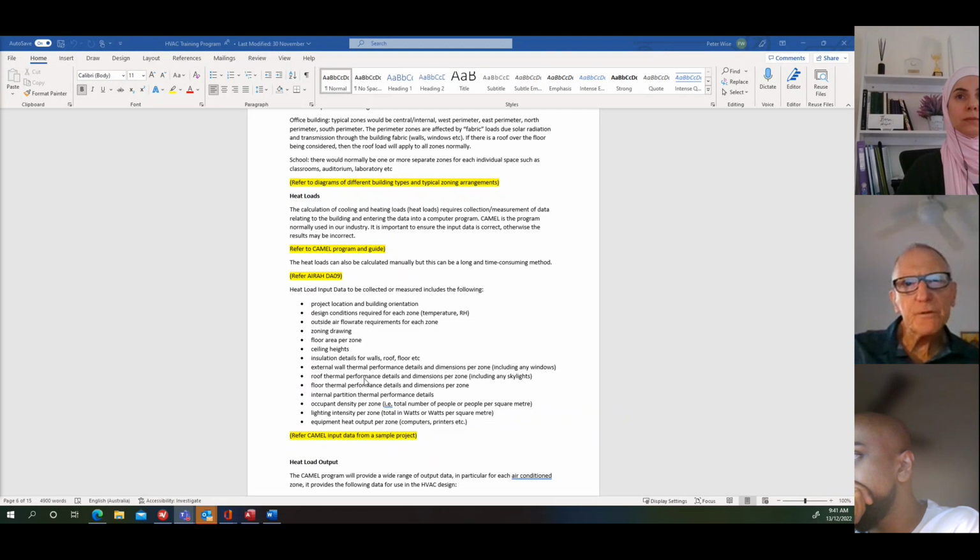A U value, well, you can look up the definition in DA09 as well, but it's basically the coefficient of thermal transfer. So the equation for heat transfer through a building element is the U value times the area times the delta T. So UA delta T. It's a simple way of putting it, but the solar effects have an effect on the actual temperature difference.